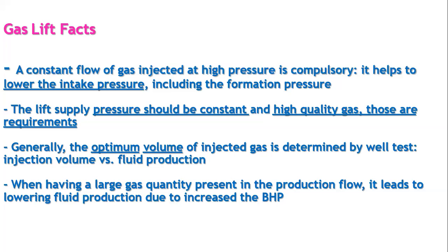The idea is to define if we have a central system, a gas compression, and we are distributing across the field. We have to bear in mind that we have losses along the tubing, and so the wellhead pressures for the wells are different. Those considerations should be taken into account too, in order to really optimize the productivity from each well.